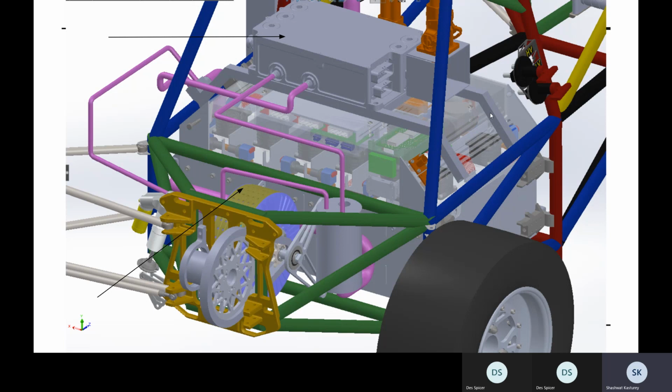What's the temperature that you want your batteries at? So as per the rules, every battery cell has to stay between 45 Celsius and 60 Celsius. And this is actually a pretty happy range for the cells to discharge at anyway. 60C, for reference, is across engineering considered too hot to touch, and above 60C your cells start to get toasty.